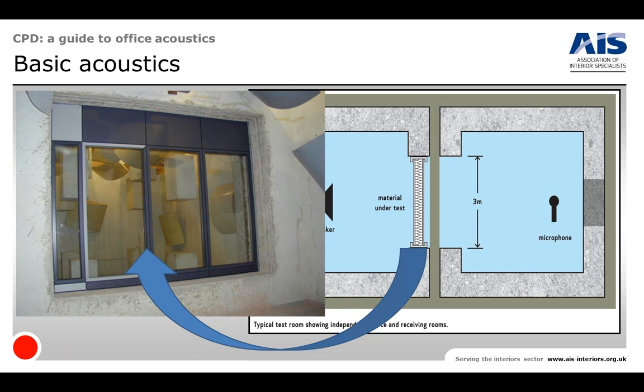If you ever want to hear a conversation going on behind a door, you'd go to an old-fashioned keyhole, because of course the sound will come through on that space. So again, a lesson early, when you come to look at partitioning and it being installed, it needs to be really as airtight as possible to make it as sound insulating as possible. I'm desperately trying to avoid the word soundproofing, because you can't soundproof a room, not really, possibly a recording studio, but avoid the word soundproofing if you can.